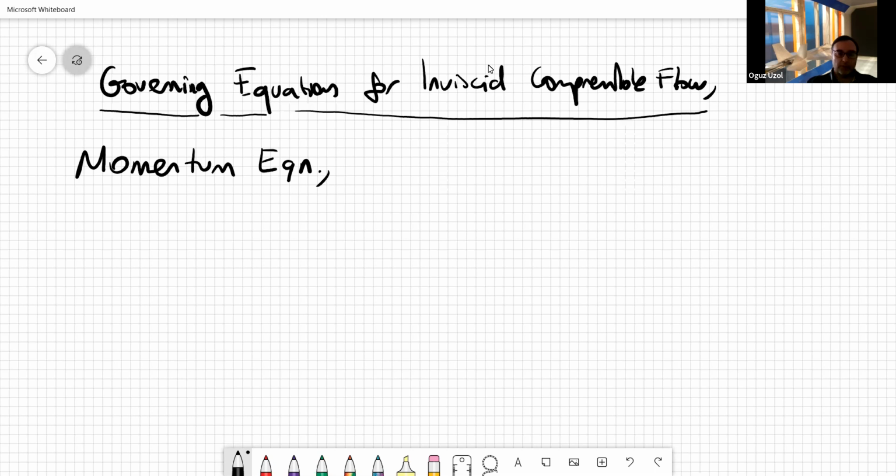So the momentum equation is also like that. What we are basically doing is applying Newton's law of motion, sigma F equals ma, to this fluid element as it moves around with a certain velocity. Since it has a mass, basically we say that its momentum should be conserved. What does that mean? It means that if its momentum changes while it's moving along, that must be due to some forces acting on it. More than probably one force, so there may be many forces acting on it. So the net force must be responsible for the change in momentum.